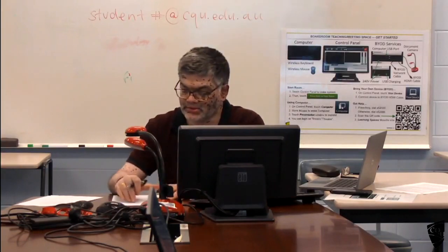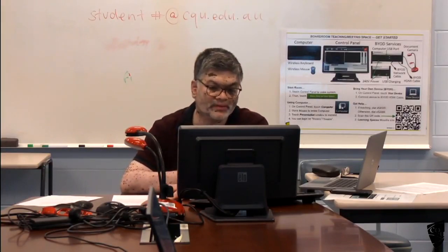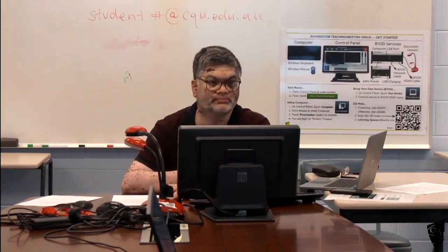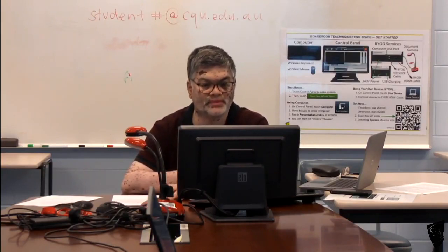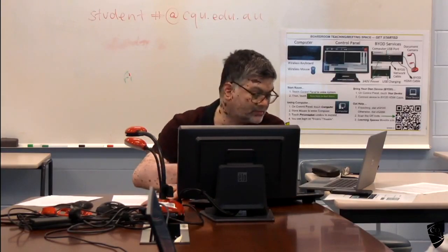So I need to design this strip. So I need to find out the bending moment first, to design reinforcement, because I already decided the depth. Depth is okay. Now I need to design the reinforcement. If I need to design reinforcement, I need to find out the bending moment. Okay, so we use some different approaches for bending moment for 1-way and 2-way slabs. This one is a little bit different.